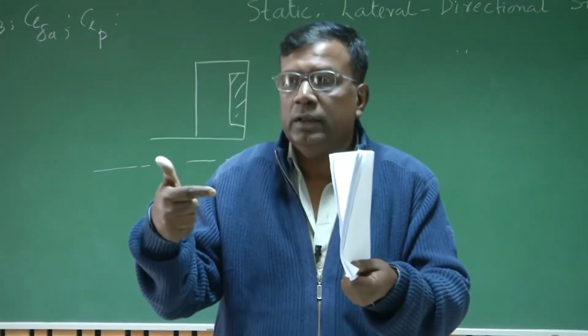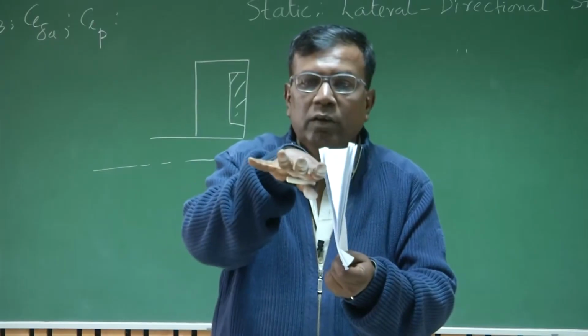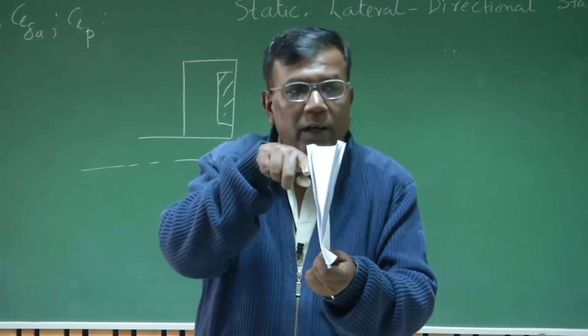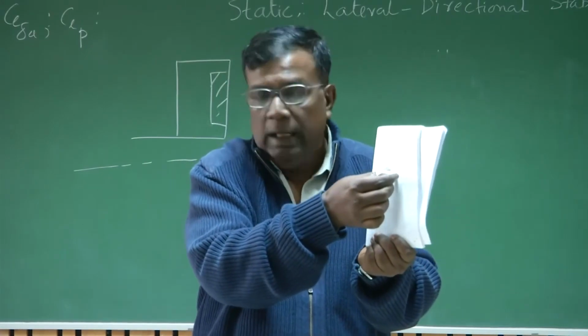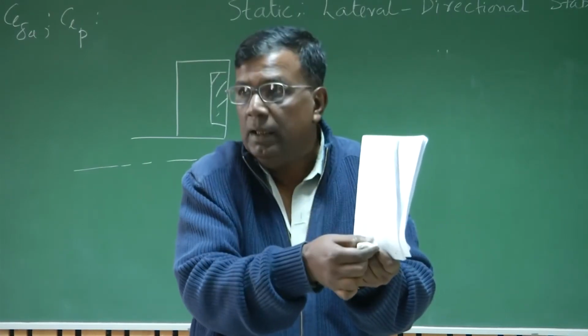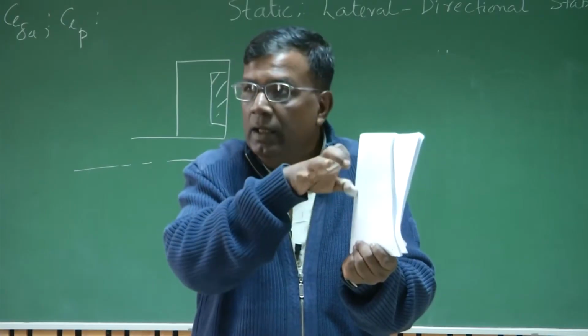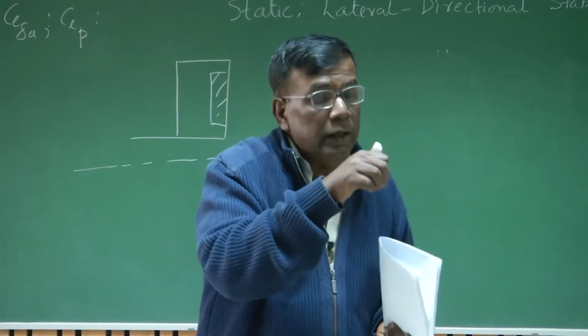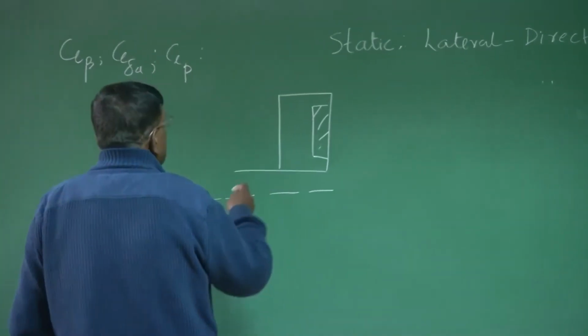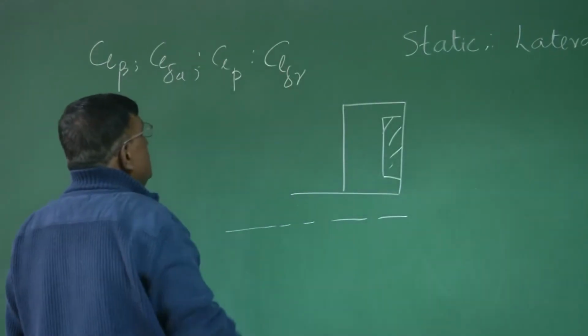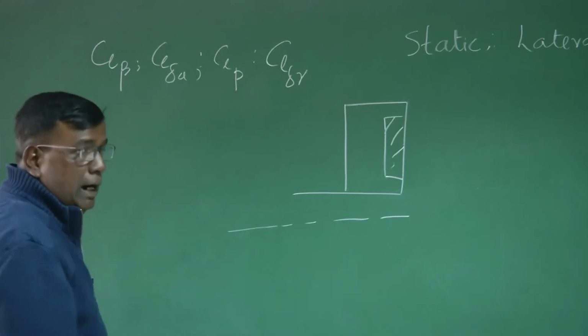This force will do what? One is it will give a yawing moment, and there is what? Because this force acts somewhere above the center, at a distance from the center line of the fuselage, this will also give a rolling moment. So you can use a rudder to generate rolling moment. We denote this using the notation CL delta R.